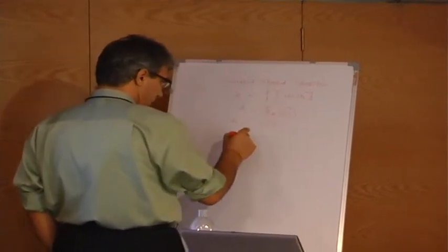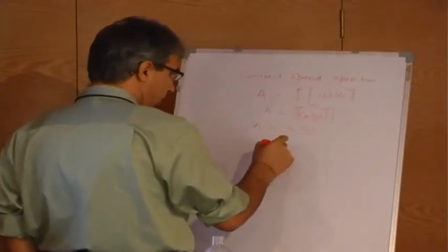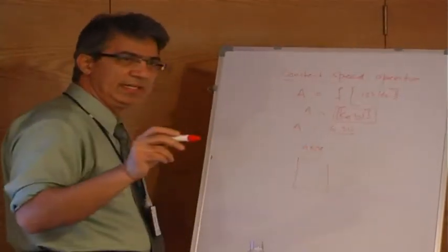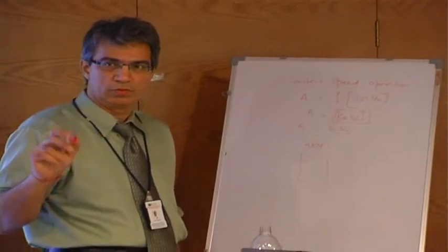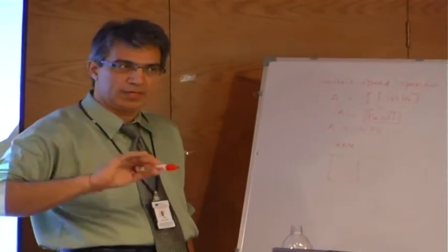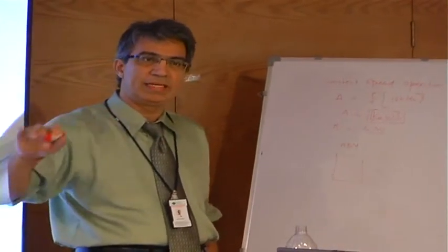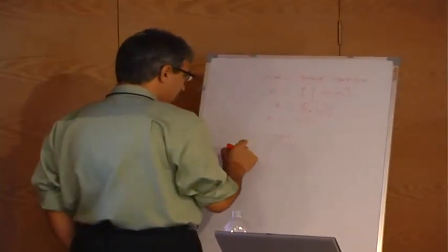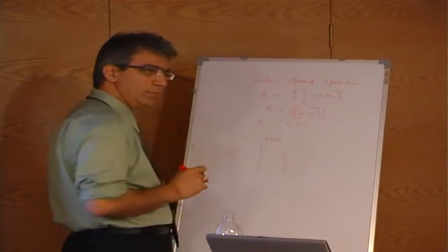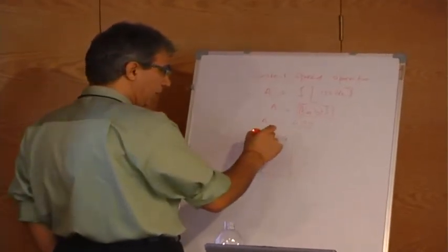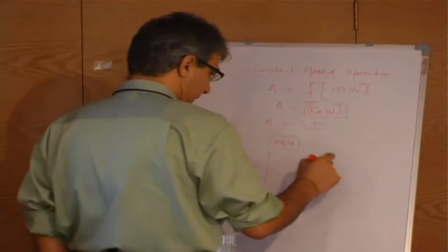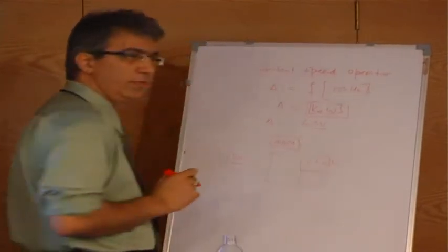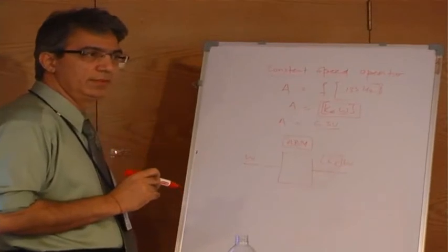You can do ABM, which is analog behavior model, and we'll see that in induction motor drives, when we do the simulation, where we demonstrate how you can incorporate speed into your model. But this one is a constant speed model, but you can take omega as an input, and with an analog behavior model, you're able to get Ke omega. And then Ke also is a constant you can define.